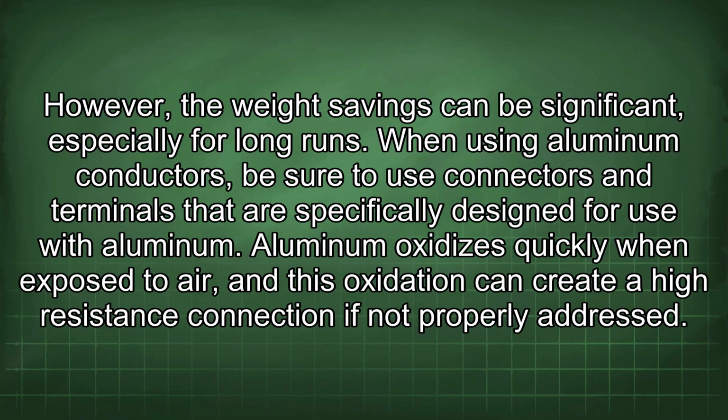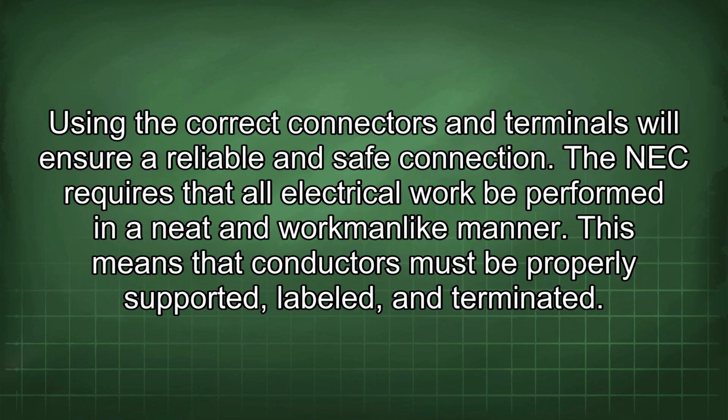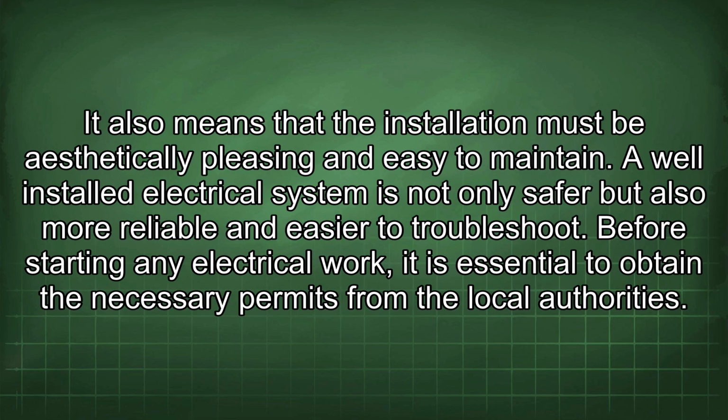When using aluminum conductors, be sure to use connectors and terminals that are specifically designed for use with aluminum. Aluminum oxidizes quickly when exposed to air, and this oxidation can create a high resistance connection if not properly addressed. Using the correct connectors and terminals will ensure a reliable and safe connection. The NEC requires that all electrical work be performed in a neat and workmanlike manner. This means that conductors must be properly supported, labeled, and terminated. It also means that the installation must be aesthetically pleasing and easy to maintain.